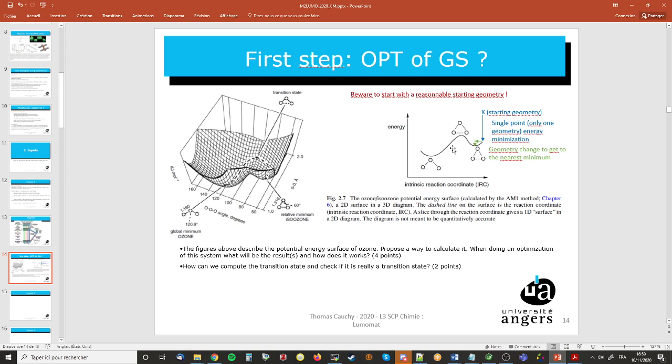The answer is when you force a point group symmetry. So the most typical approach is, for a molecule, if you draw a planar molecule, Gaussian will detect that you have a planar molecule, so you have a symmetry plane, and it will force this element of symmetry. And if your minimization needs to break this symmetry element, it will be stuck in this point group symmetry. So it will not optimize to, for example, the global minima.